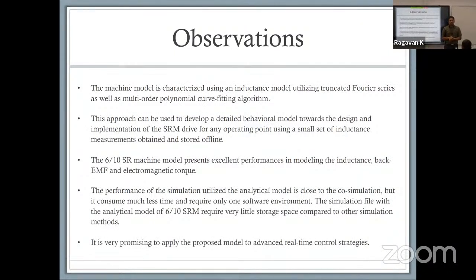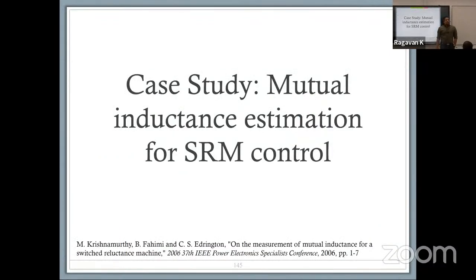The challenge or the limitation can be that you do not have the initial geometric design from the manufacturer, which a lot of manufacturers won't give you, especially if you're talking about an end user application type product. So essentially, we found out that it's quite possible. It can be done, and this method can be used a step further for fault diagnostics and isolation. Because if you know what the healthy machine is supposed to look like, now you can start to look at the harmonics, look at the frequency spread, and identify if there's a bearing failure or something like that. So that's where we're going to stop here.